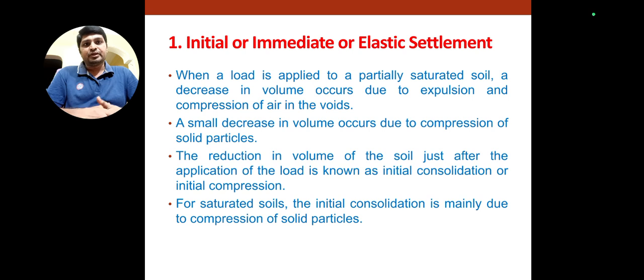A small decrease in volume occurs due to compression of the soil particles. The reduction in volume of the soil just after the application of the load is known as initial or immediate or elastic deformation, settlement or compression. For saturated soils, the initial consolidation is mainly due to compression of the solid particles.